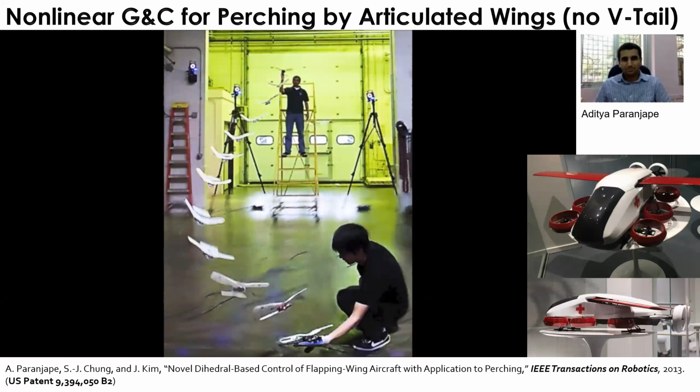A nice extension of that is, what about a swarm? Because you have downwash coming out of each drone in a swarm, you cannot really fly multiple drones close to each other, since there is an enormous amount of downwash. Similar to using the neural network to predict and feedforward cancel the ground effects, we can also use a deep neural network to predict the downwash. The key idea is the spectral normalization, so that you can design a smooth nonlinear tracking controller when you have multiple drones. It's called Neural Swarm, and it was presented at the 2020 ICRA.